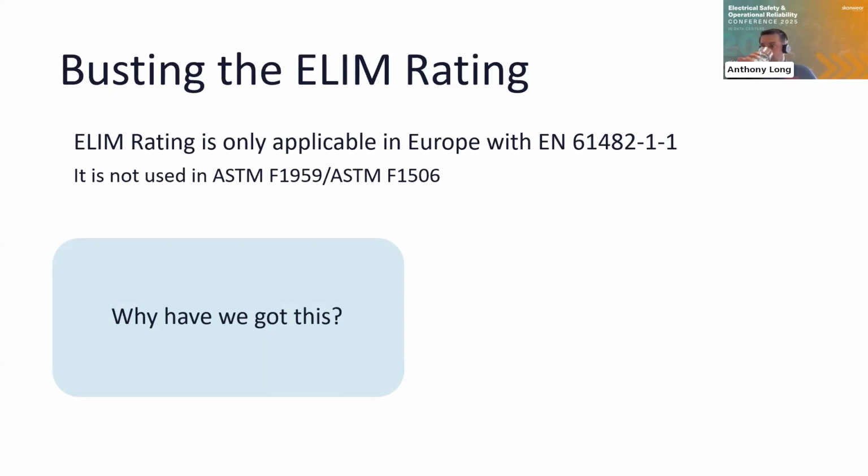There's no other rating for that, so there's no probability. It's very defined. At the same time, the arc flash is also very defined. You have a box with conductors inside the box, and a fabric 30 centimeters outside the box. The arc flash is only generated across a small gap and ejected out of the box to the fabric that's waiting to receive it. So the arc flash is very, very centered on the garment itself.